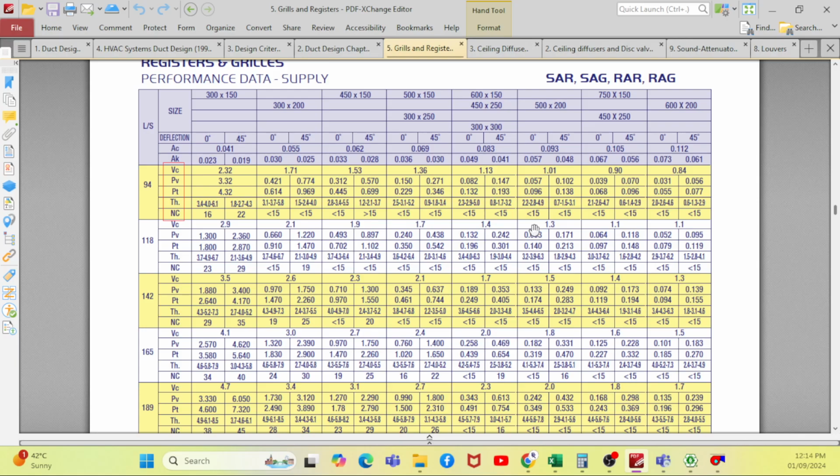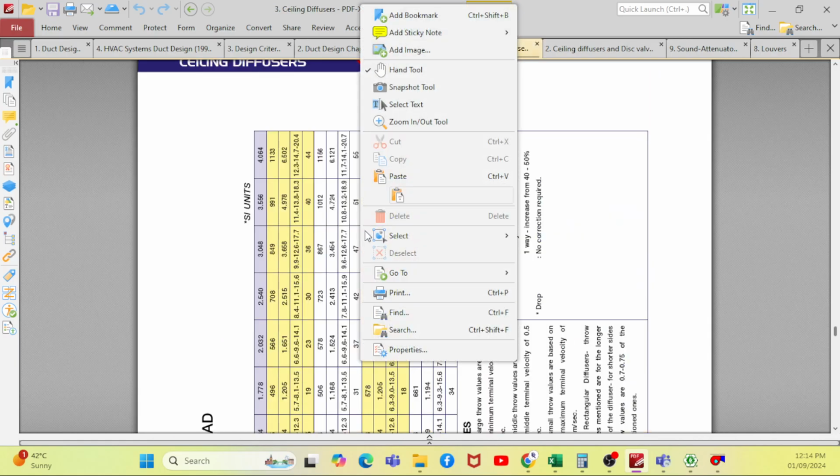When you have a larger pressure drop or large ducting, or you have different types of accessories, then you can go with different methods, like different static pressures you can select. But normally, as a fan coil unit, you can stick with 50 Pascal itself. The same method you can apply for all the AHUs, FAHUs, or any of the general fans. If you have ceiling diffusers, the same method.